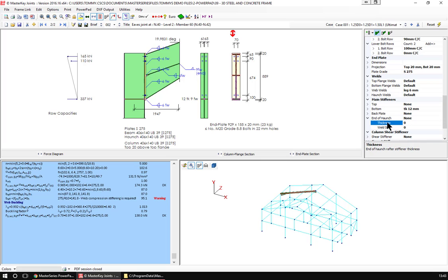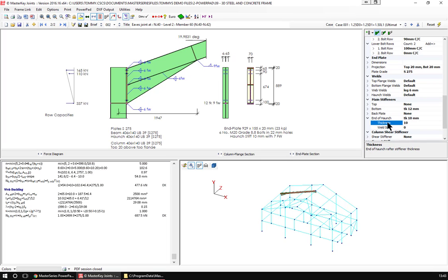So I'm going to slip in a wee 10mm stiffener. And there we go, all 8s, 8 6s, so 6 welds and a 9. And all I want to do at the end of the haunch under welds is tell it the flange weld is also a 6mm, and that told me that for a 6mm that connection's okay. So we have that full integrated connection design. One more connection just before we go.